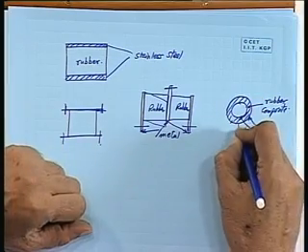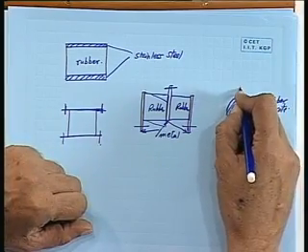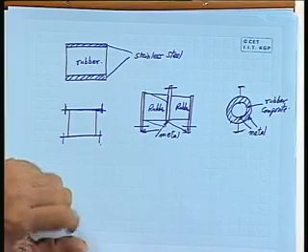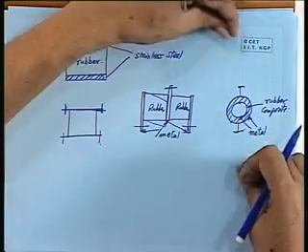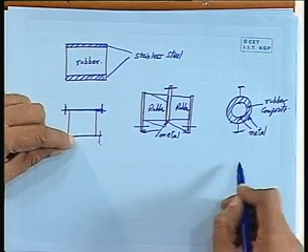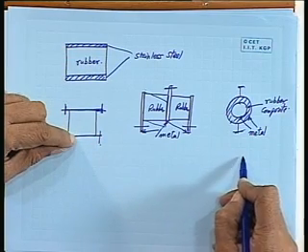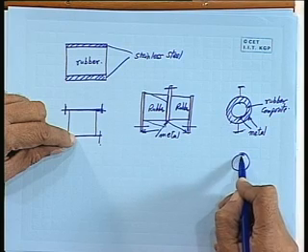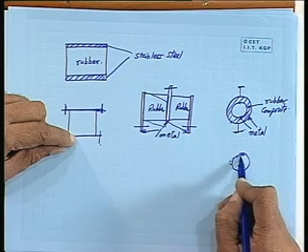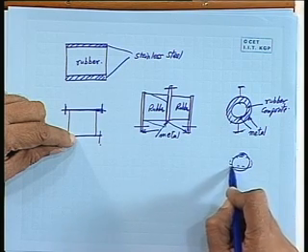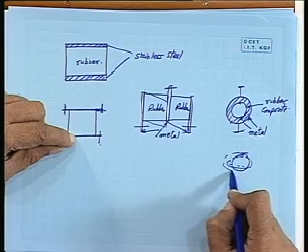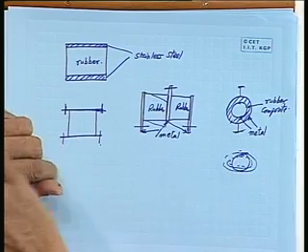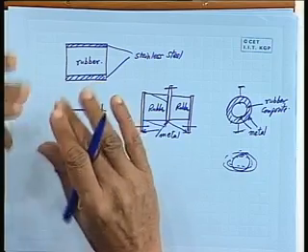Now, you can connect this to the foundation, you can connect this to the equipment here. So, in this case what happens is that when the displacement takes place, the circle will get deformed to a sort of an ellipse, and the rubber inside will be there, and then another ellipse. So, this is basically coming in the bending mode.